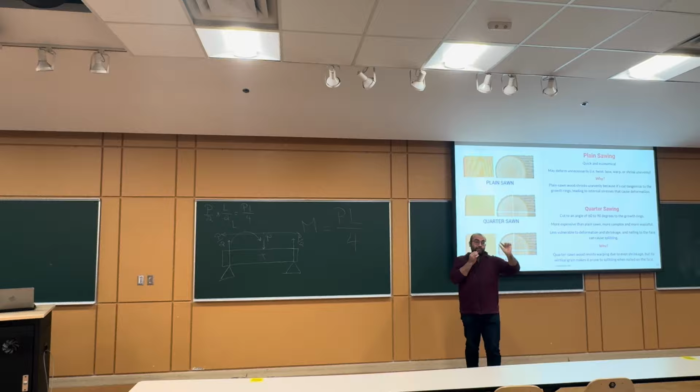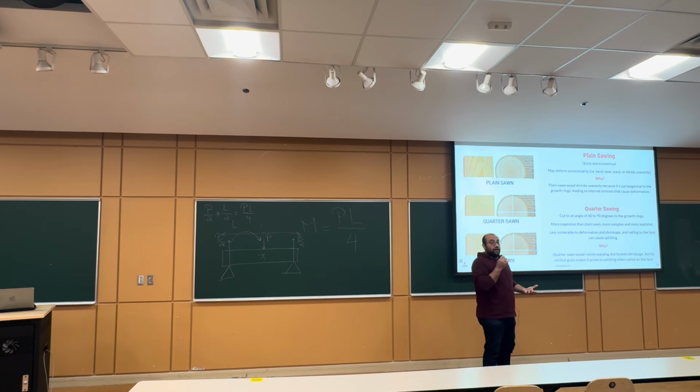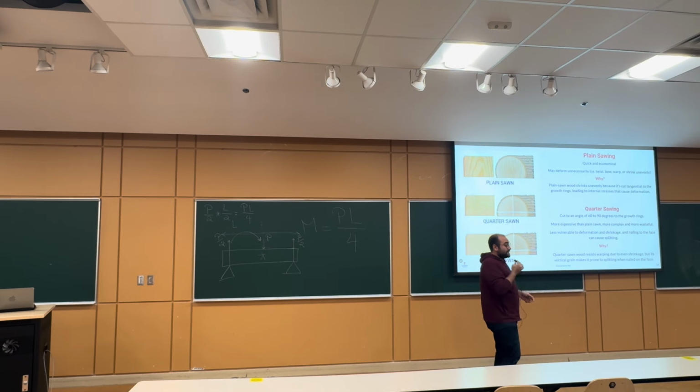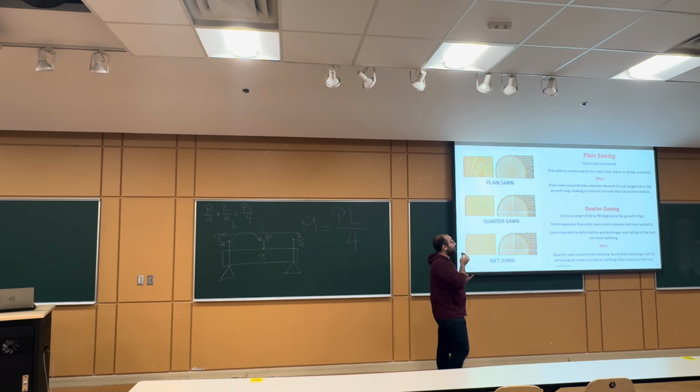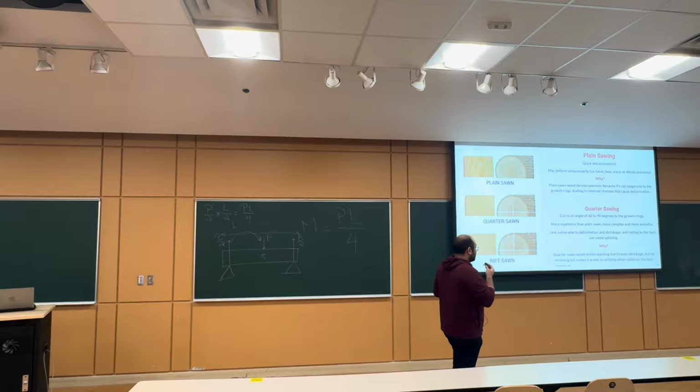are cutting along the direction of growth, from the inside to the outside. So you are having a regular part with homogeneous properties when it comes to shrinkage. So we are less prone to unneeded deformations. And another strength here is that when we do nailing, this material will not split easily. But the product of plain sawing can split easily if we apply nailing to the surface or to the depths of the material.